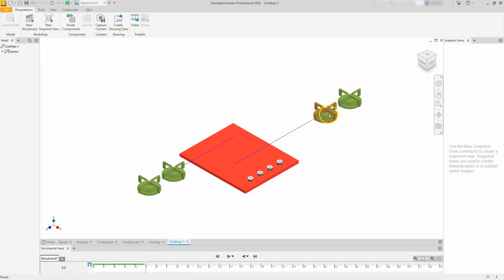Now maybe I wanted that one a little bit closer. So we can change this. If this number is wrong or you want to adjust it, underneath Scenes here, I'm going to expand that, and underneath the Tweaks button, let's go ahead and expand that one. And now you're going to see the distance. So you see that distance of 300? Let's go ahead and make that 200, and you're going to see that this moved forward, right?